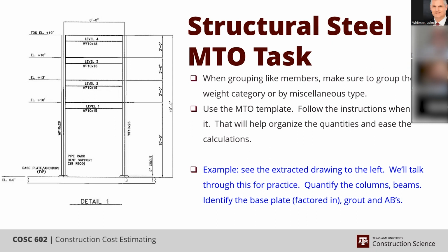There is nothing to indicate that it is cross bracing. It's just 2 lines. I'll give you an example. S105. Mm-hmm. Because I'm used to cross bracing on the side, not on the bottom, not on the plan view, but on the side view. You know what I'm saying? Oh! You're talking about the plan view. I thought you were talking about the side view. Yeah, if it's cross bracing, I'm guessing they will put the section on it. No, I'm pretty sure that one's cross bracing also. It's keeping it square. But there's no detail of that in there.